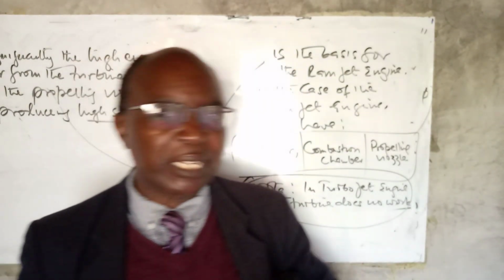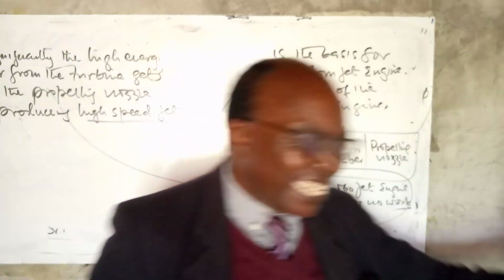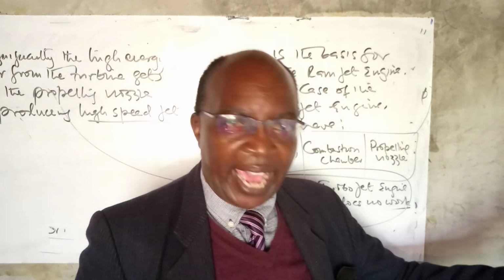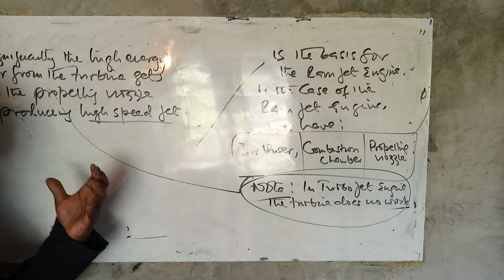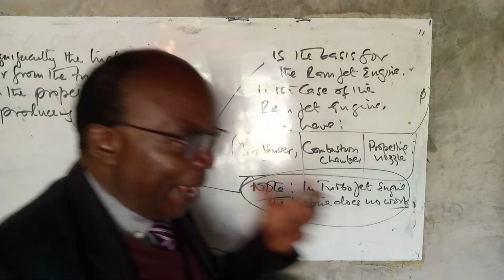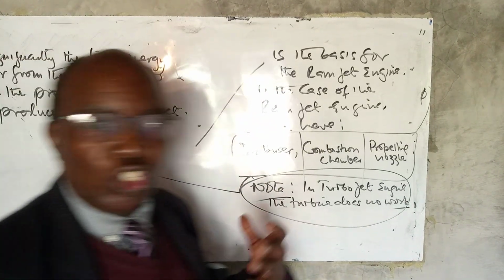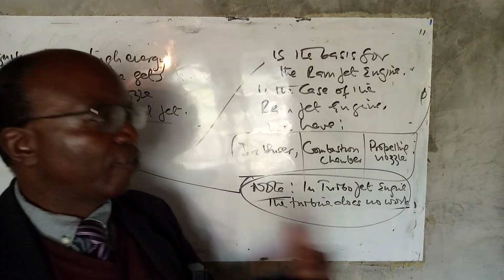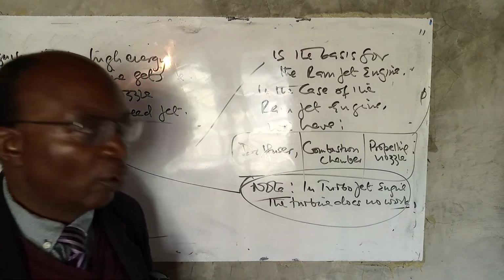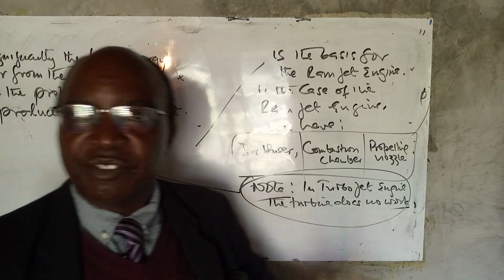And so, as I mentioned, when we did our earlier discussions, we had a stationary duct. And so we were talking about absolute velocities, which are velocities relative to the Earth. But now the duct is moving. And so, for example, when you're talking of the ramjet engine, for the pressure to build up, it means you have to initiate a motion. And of course, we have the piston engine, which will do that because that piston engine drives the propeller.